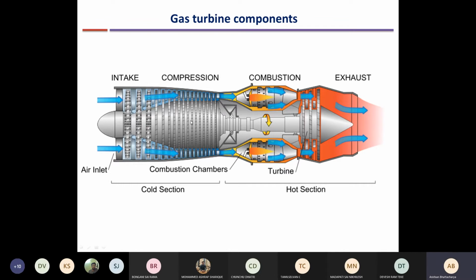What is the basic reason for this? Why do compressors require much higher work input as compared to pumps for the same increase in pressure? Sir, because of the low density of air as compared to water in the boiler. Because of the low density of air. Yes. So how does low density of air affect it? Why will low density lead to more work input? The specific volume is very high, so delta P times V is very high. Specific volume is very high.